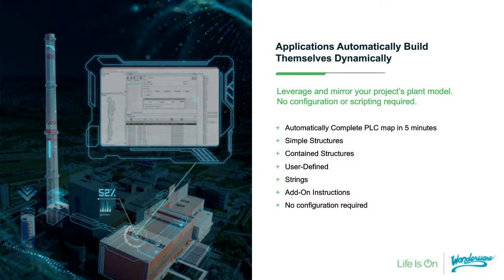These auto build operations can actually go directly and inspect the PLCs or the devices that you may have in your organization and extract the information like simple structures, contained structures, user-defined structures, strings, add-on instructions, and with no configuration required, can automatically replicate that asset model, that data-driven model that builds the rest of the navigation content that I've referenced.